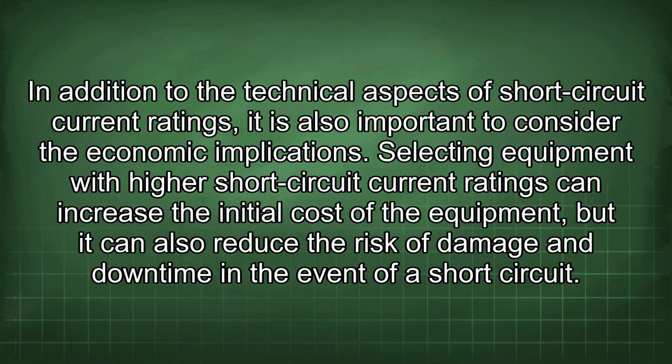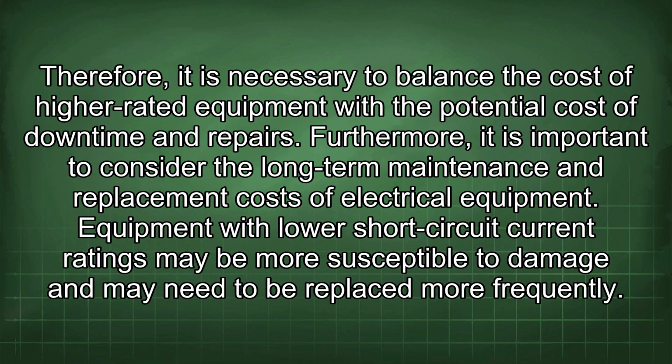In addition to the technical aspects of short-circuit current ratings, it is also important to consider the economic implications. Selecting equipment with higher short-circuit current ratings can increase the initial cost of the equipment, but it can also reduce the risk of damage and downtime in the event of a short circuit. Therefore, it is necessary to balance the cost of higher-rated equipment with the potential cost of downtime and repairs.